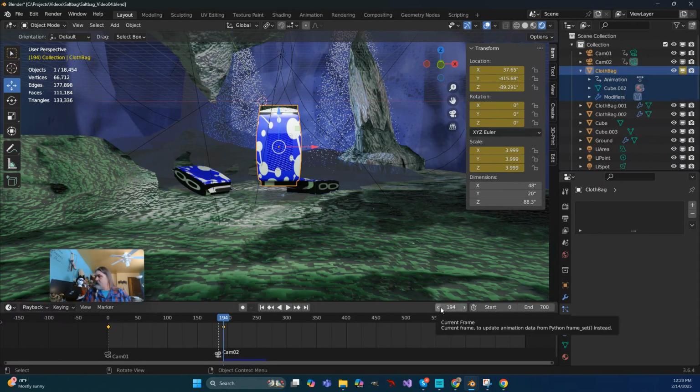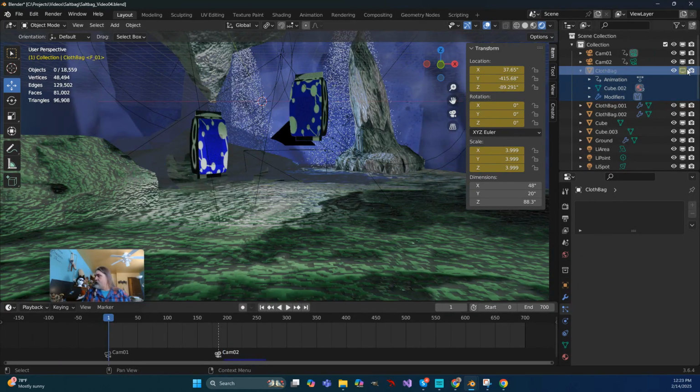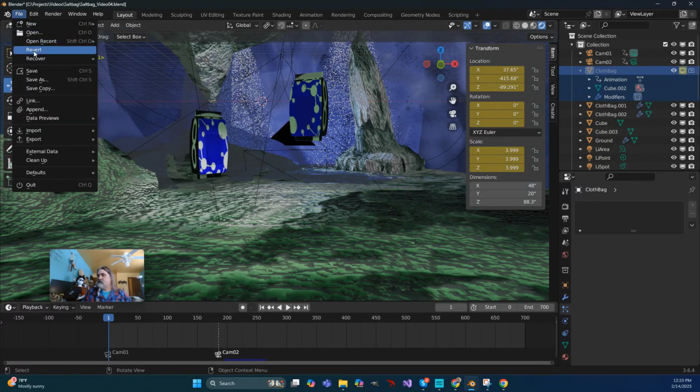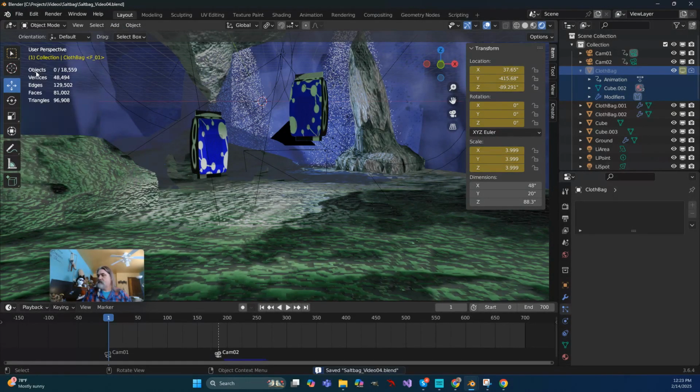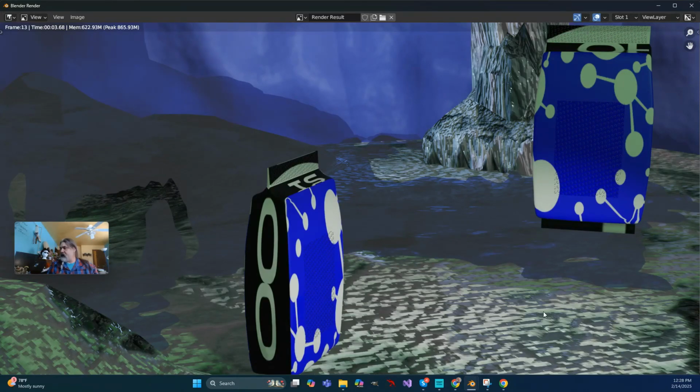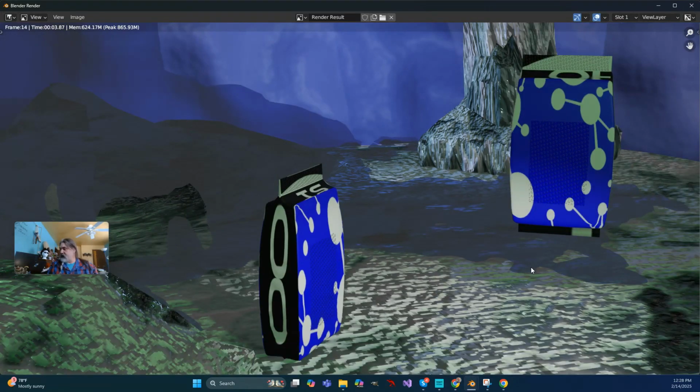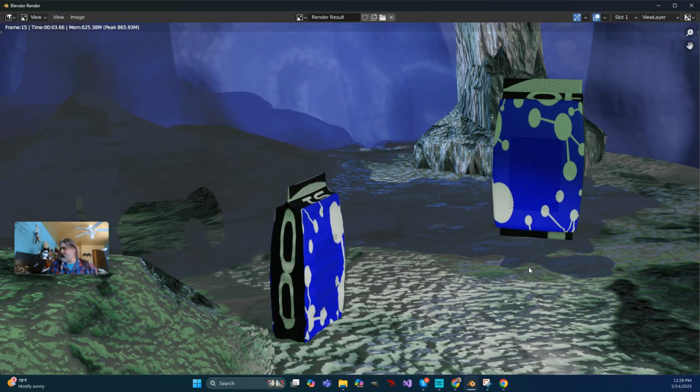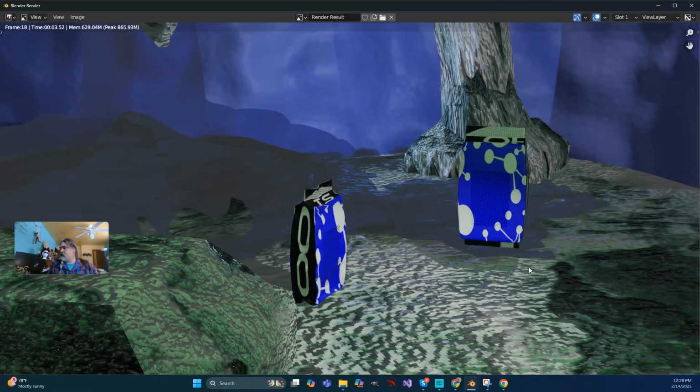Insert. I'm going to select each of these items underneath, and do an I to insert. Shift I. I'm going to go back to frame 1 and attempt to toggle these off and see what that gets us. So now it appears that that bag is not rendering. So that's great. We were able to insert the keyframe by holding down the shift key and adding the animations and so forth to the do not render list.